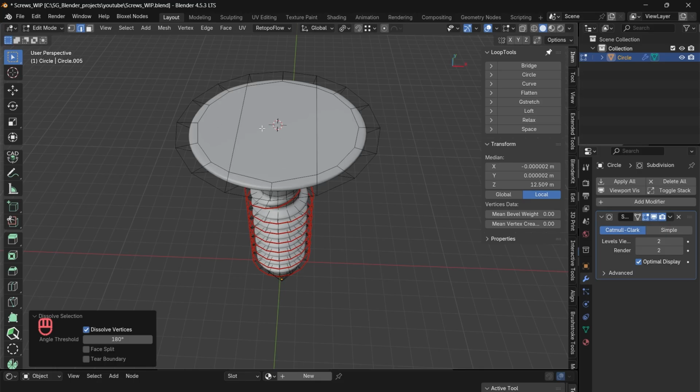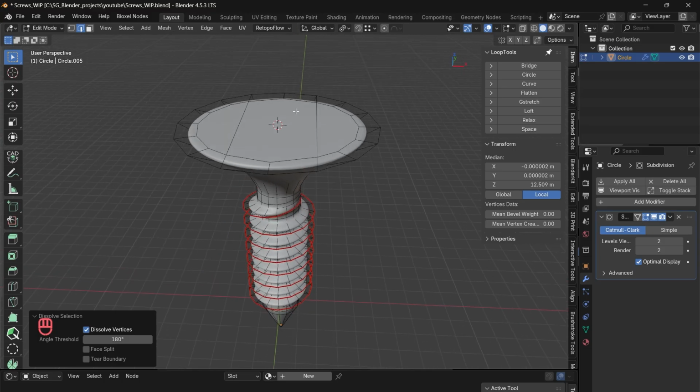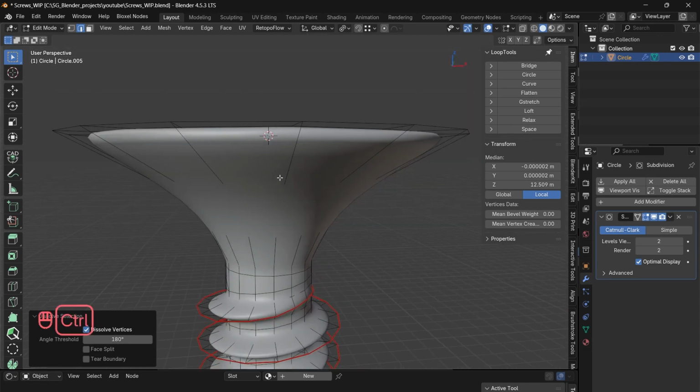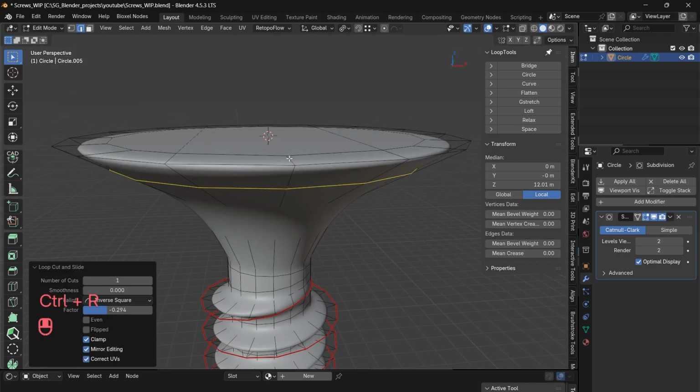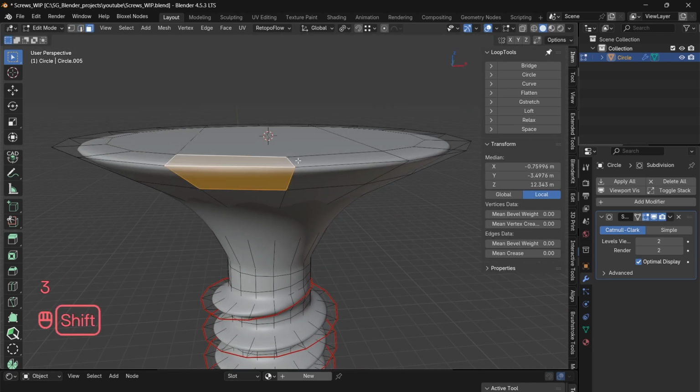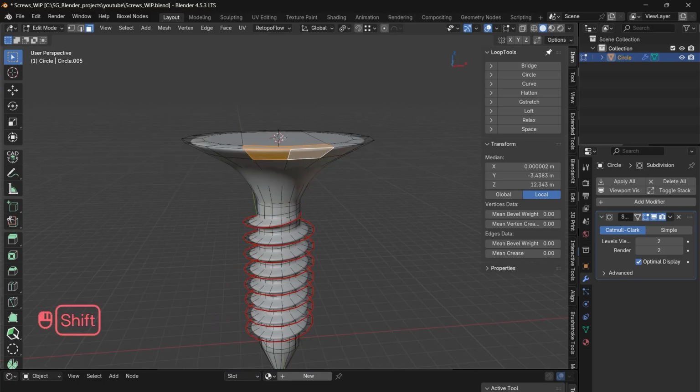With 32 vertex, it will be easy to create a sharp corner out of it, but with 16 vertex, it is really not possible unless you use Boolean cut. But that will have its own problems. Okay, so let me just quickly create a simple cut out of it.